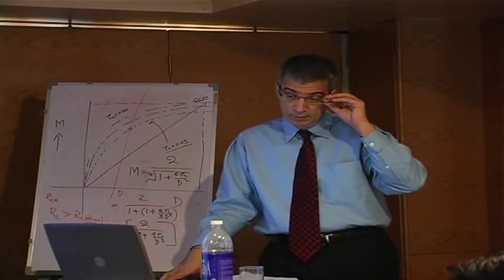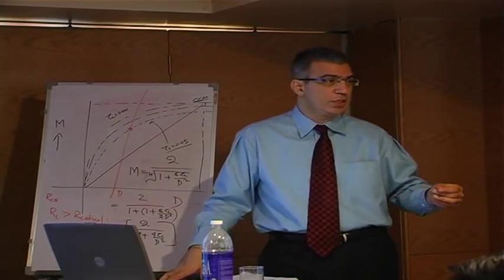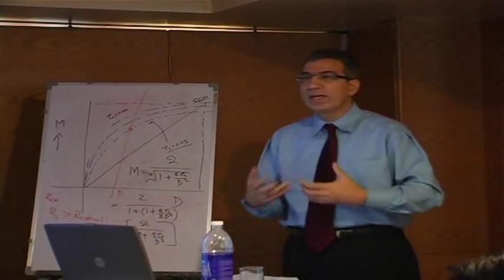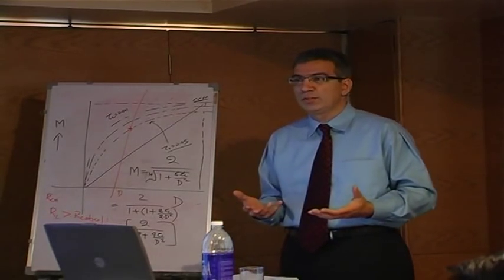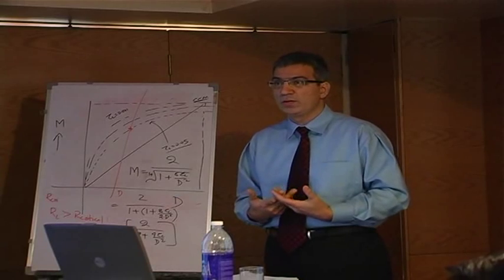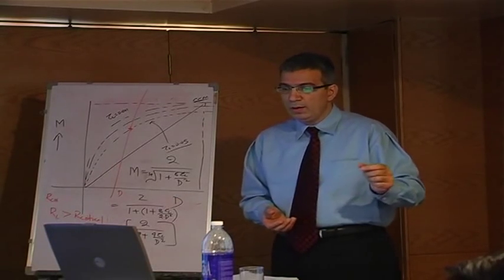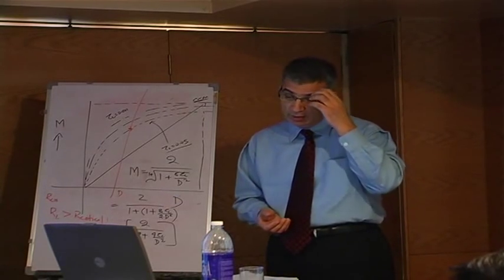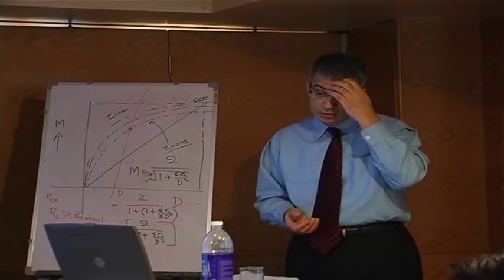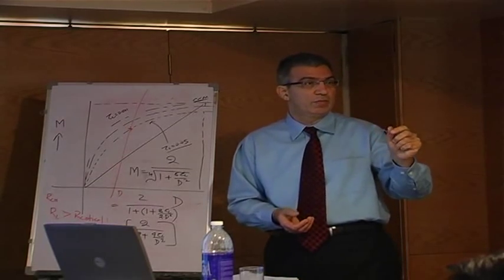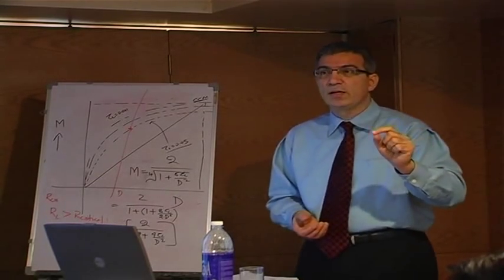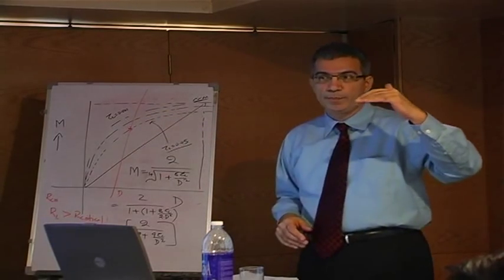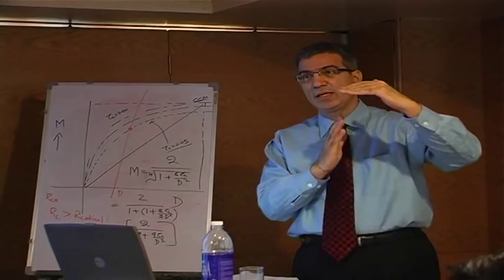So unless you have specialized equipment when you make a power supply, you could not really determine the transfer function. You have to build a prototype, and then only you could determine the transfer function. So what has happened is, over the last few years, several attempts have been made to develop what is called a small signal model of the switching element we were talking about, which included the switch and the inductor.